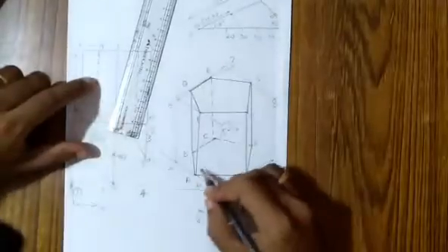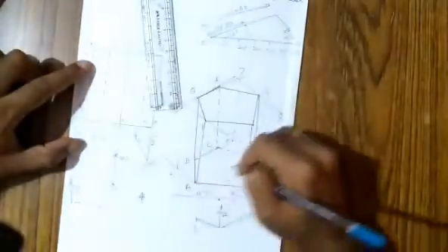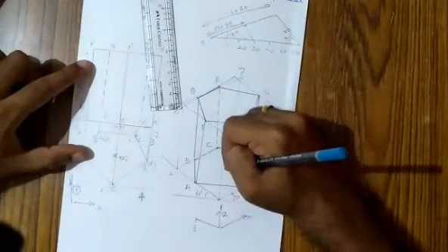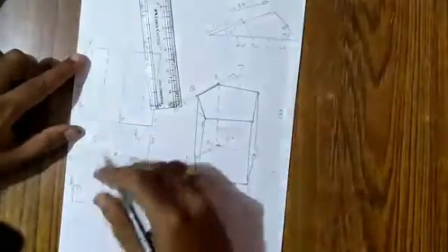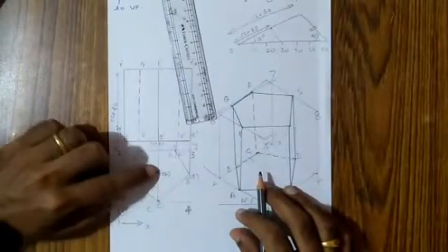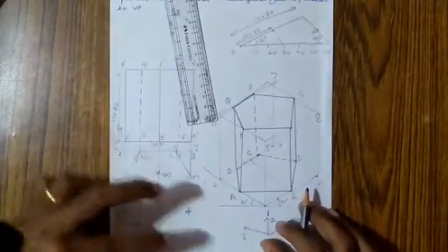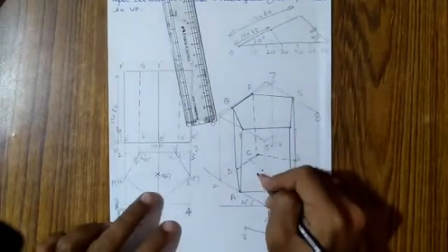It's not going to be on AD, but what you have to do is draw a parallel line through E. You have to draw a parallel line through E, parallel to Y direction. Okay, and on that line you get this distance from E to O. So you get this distance and you mark it over here. So this is your point Z.